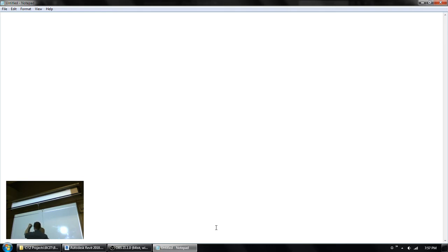So this thing is 4 inches, this is 5 inches, and so now your beam, in terms of where it sits from the level, is down -9 inches. These joists are down -4 inches because they are at the underside of the metal deck.